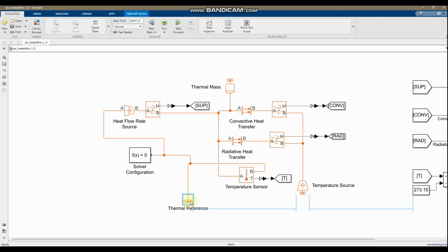But just let me go through a few of the things which are unique to the temperature domain. So, thermal reference is the 0 Kelvin point. Nodes on a network are kind of like interfaces between objects. The through variable is the rate of heat transfer, and the across variable is the temperature difference across two nodes.